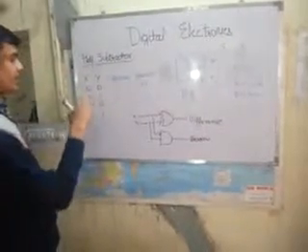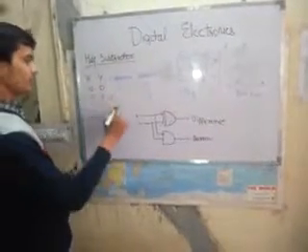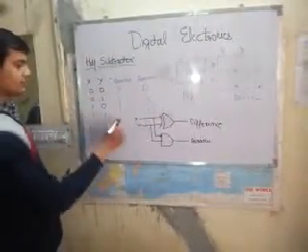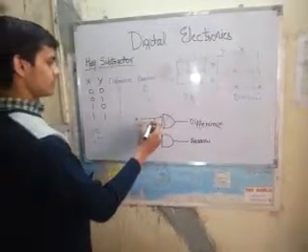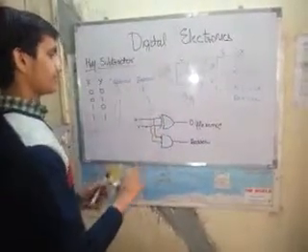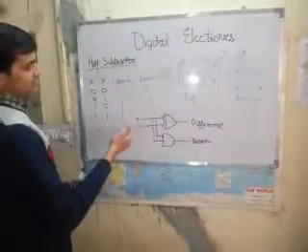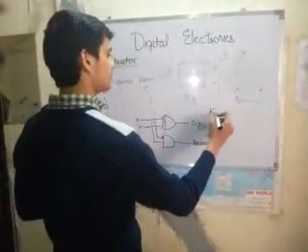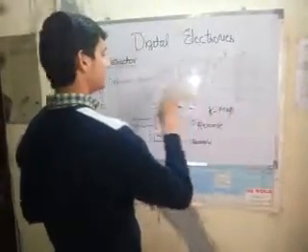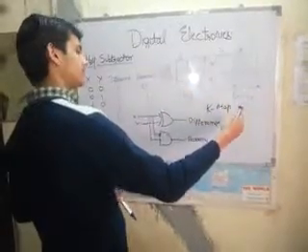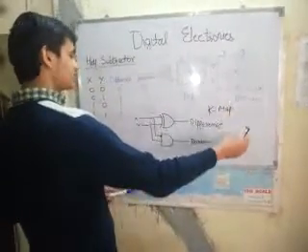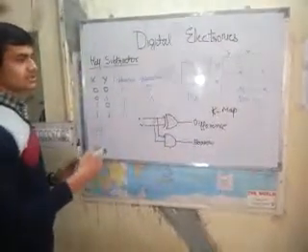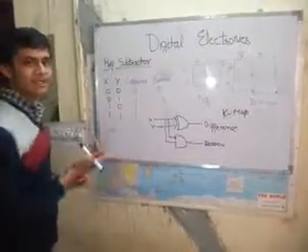Now while subtracting x minus y, this is 1 minus 0, we will get 1 still and 0 borrow. And subtracting x minus y, 1 minus 1, it is 0, and the borrow is also 0. Okay, so now we will use this truth table to construct K maps. From these K maps we will derive equations, and then from these equations we will finally arrive at the logic circuits. These are the basics for studying further complex problems that are asked in IES and GATE.